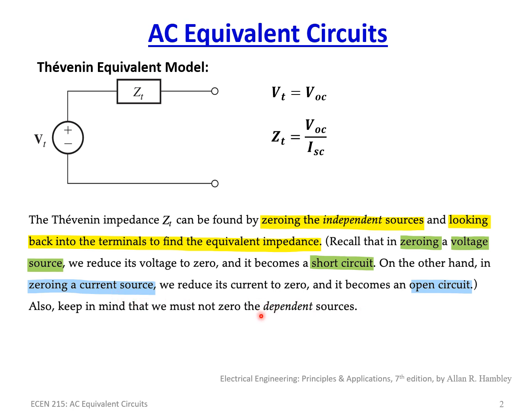Now, if you have a dependent source, you can't use this method. You have to continue to use the approach of first finding the open circuit voltage, and then applying a resistor of 0 ohms, basically applying a short across the load of the circuit you're converting over.